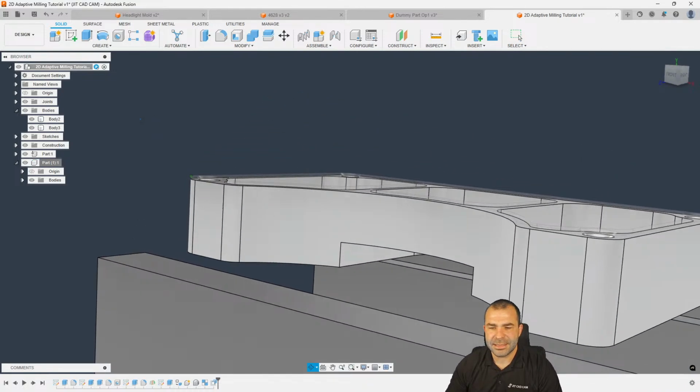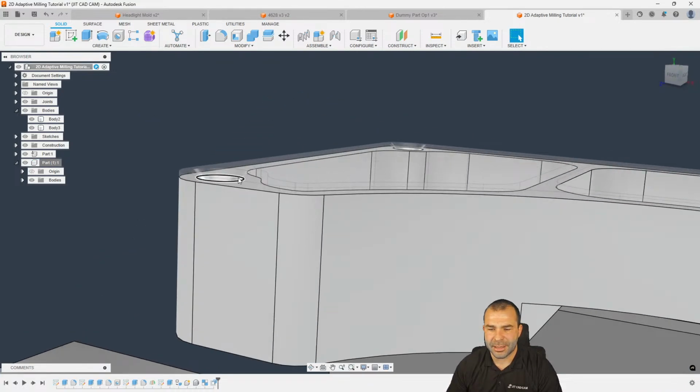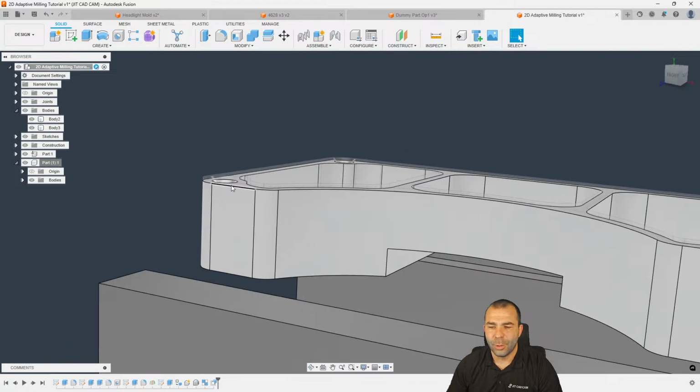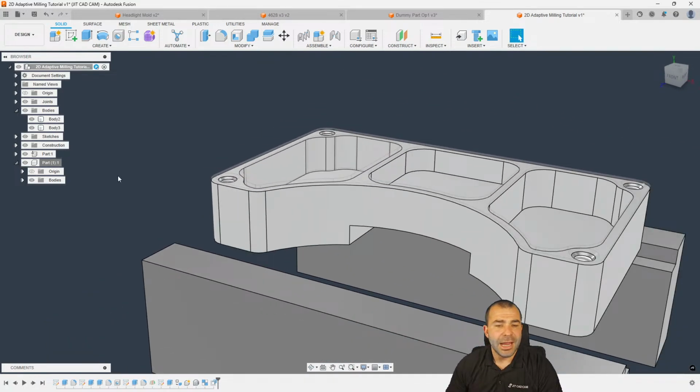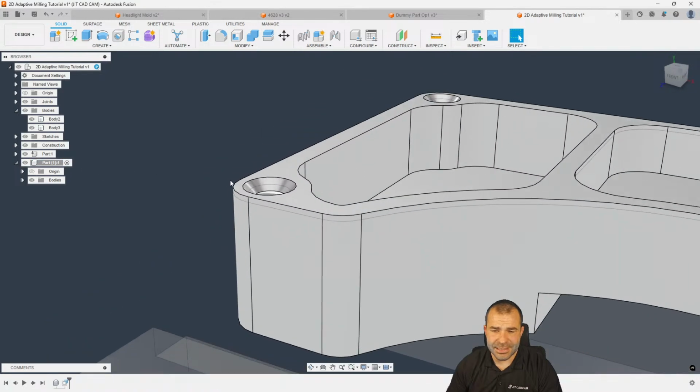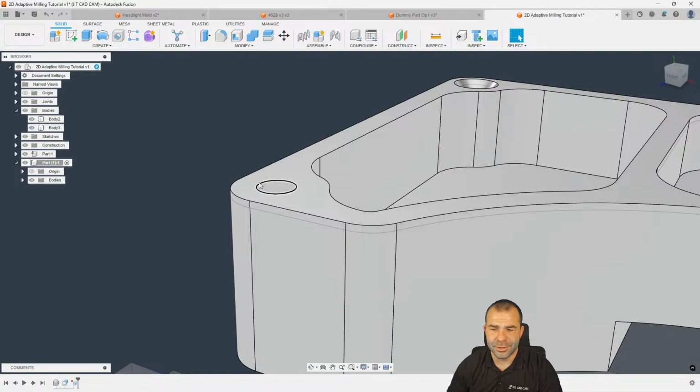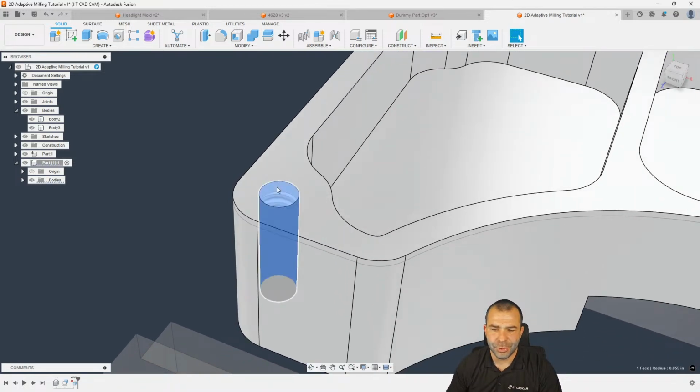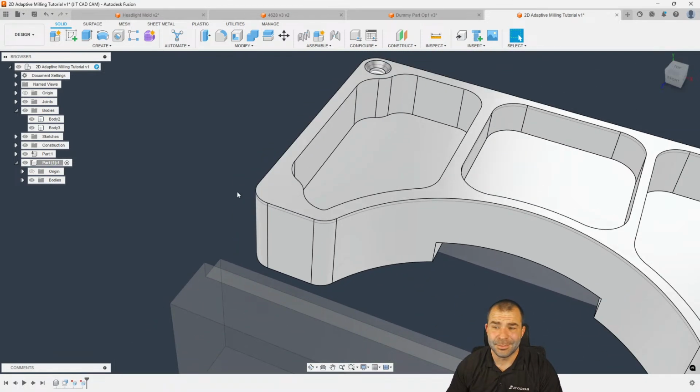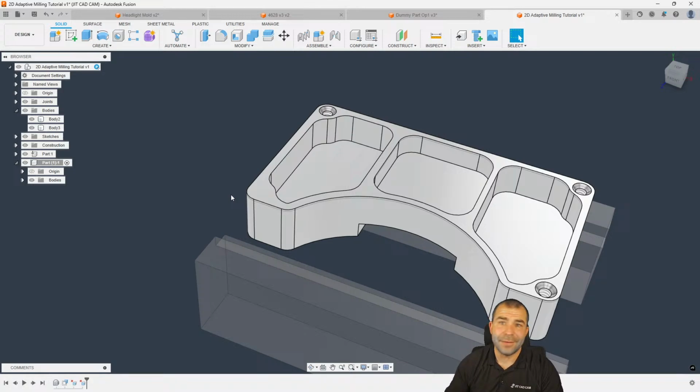So as you guys can now see with the ghosting image in the background, I have the part, one versus the other, right? And now I could take this a lot further than this, guys. If I wanted to, I could come in, remove the chamfer, even remove the drilled holes. And I'm just using the delete key. I'm not doing anything fancy, because you would obviously add these holes after the casting process.